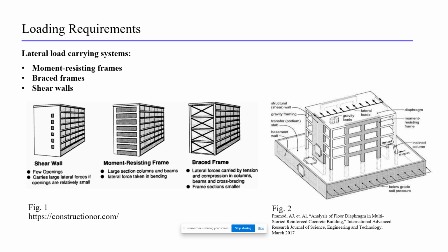Moment frames and braced frames are more commonly used in demountable equipment design. You saw that in the previous slides with the equipment. The latter, a braced frame, is the most common. As we saw in previous slides, most removable equipment utilizes that type of understructure, but you can use a moment frame. That's just a frame that resists bending at the joints. They typically require special, more expensive details, and they're more time-consuming and intricate methods of installation. So usually strategically placed braced frames are used for platform systems.